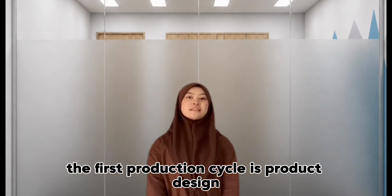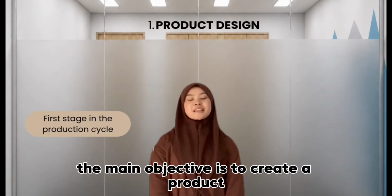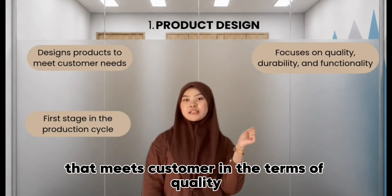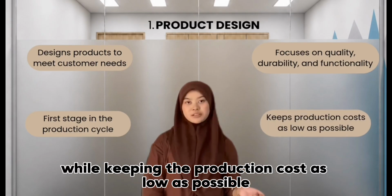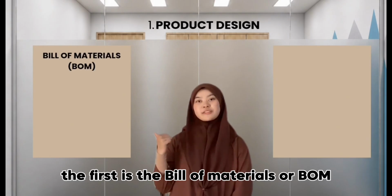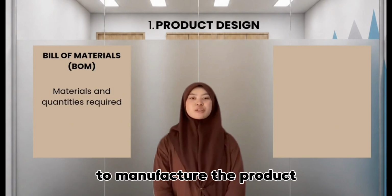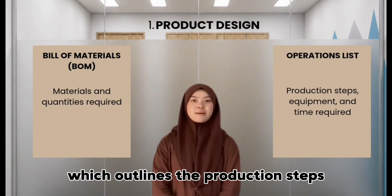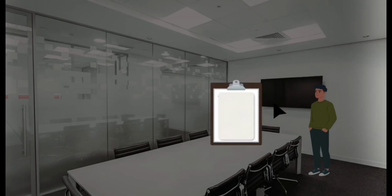The first production cycle is product design. Product design is the first stage in the production cycle. The main objective is to create a product that meets customers' needs in terms of quality, durability, and functionality while keeping the production cost as low as possible. This stage produces 2 important documents. First is the Bill of Materials, or BOM, which lists the materials and quantities needed to manufacture the product. The second is the Operation List, which outlines the production steps, equipment required, and time limit for each operation.